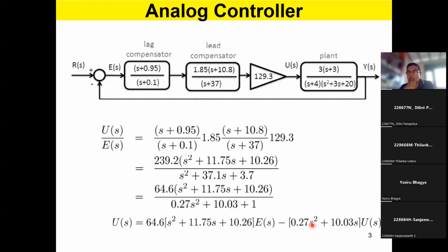Eventually, you will get rid of the differentiation altogether, but what comes in is samples. What is the error now? What was the error a step ago? What was the error 2 steps back? What was the error 3 steps back? Like that. You want to maintain these samples. After that, it's about combining samples: addition, subtraction, multiplication, division by time.